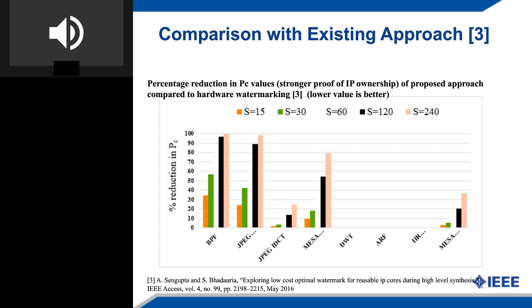Okay, now I'll move to the second half of my talk. This will focus on a new topic, securing IP cores in C systems using key-driven hash chaining-based steganography. It's a signature-free mechanism where you can implant digital evidence into your design without the involvement of any signature. It uses a novel encoding algorithm and a novel key-driven hash chaining process for generating the invisible signature-free stego-constraints, which are implanted into the design during the dual phase of the high-level synthesis process of a hardware accelerator design.